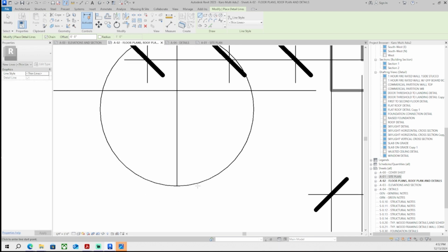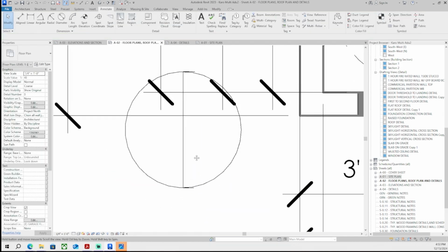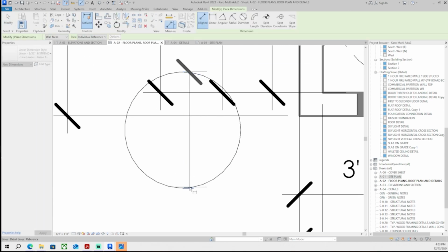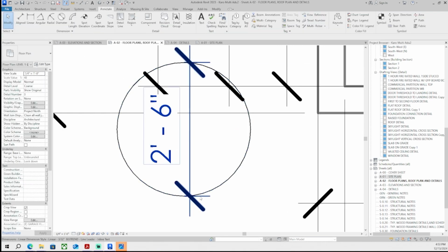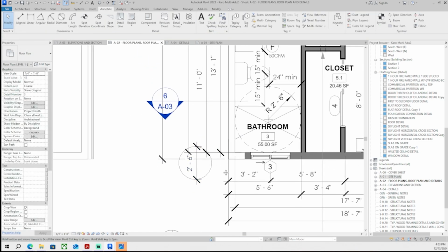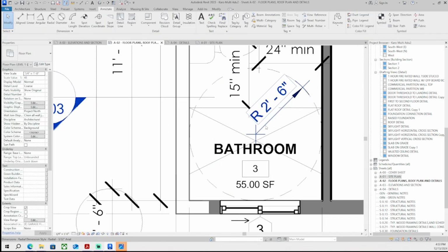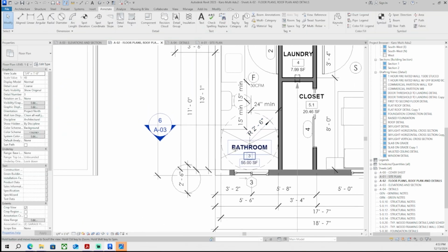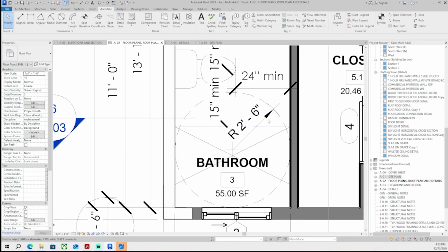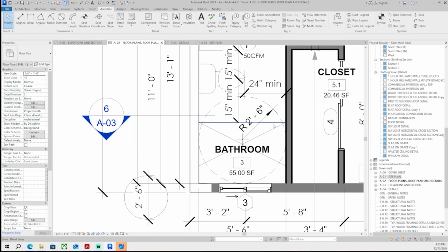But when you have traditional NURBS modeling or another kind of modeling software, that has its own advantages. You're more free with the 3D model. In Revit, in a lot of ways, you are limited. Some people who are experts with Revit will argue that you can do any kind of organic geometry in Revit also, which you can, but you need to use massing tools.